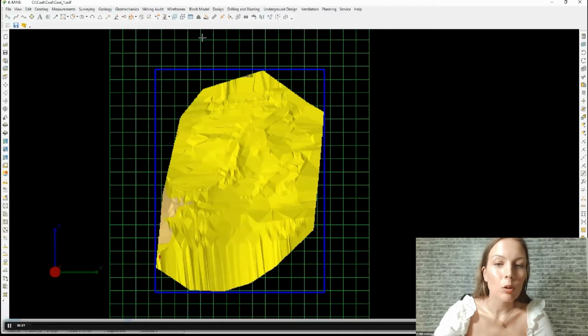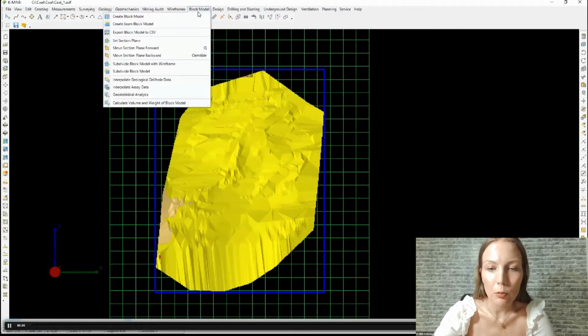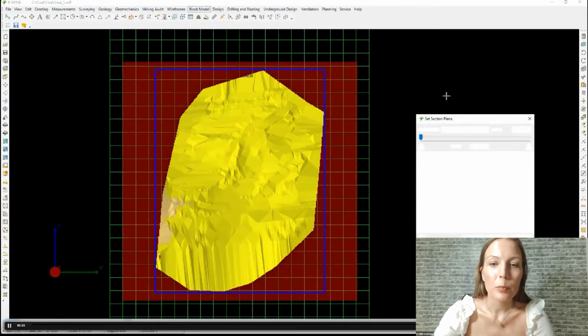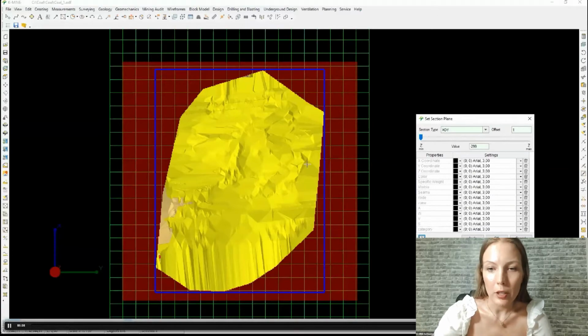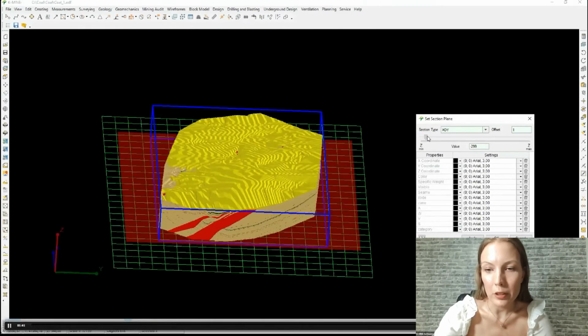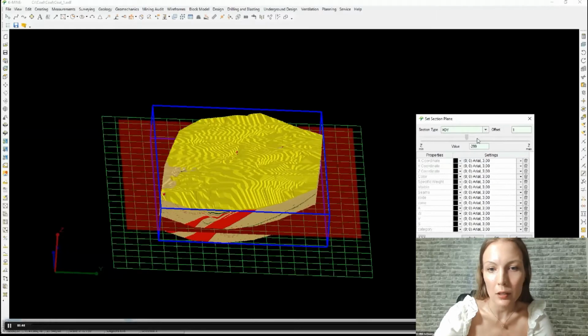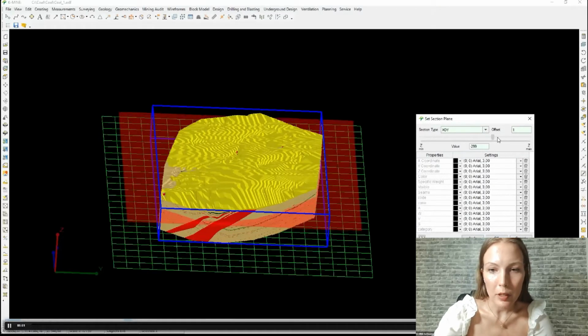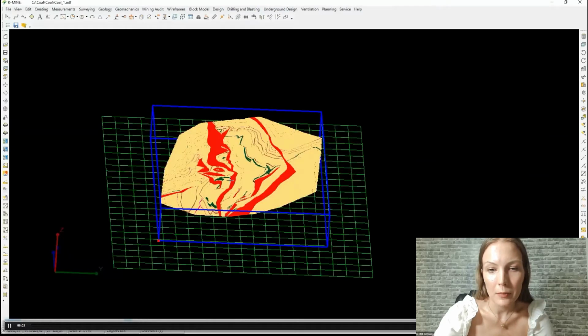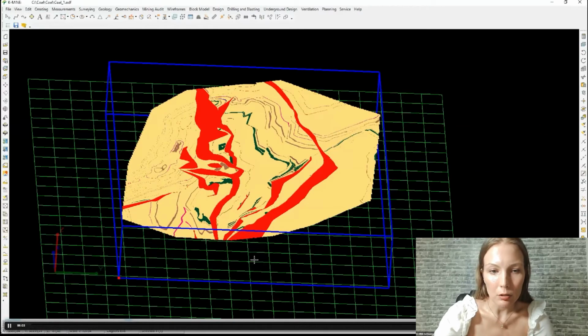If there is a case of a rare exploration network, or you need to take into consideration the operational data, it's possible to specify the elevation position of marker seam. In order to do that, you can use things like additional points of the seam's roof or floor intersections in underground mine workings, excavator bucket measurements, bench sketches, lines of seam elongation to the daylight surface, seam's floor isolines in the plan, and so on.